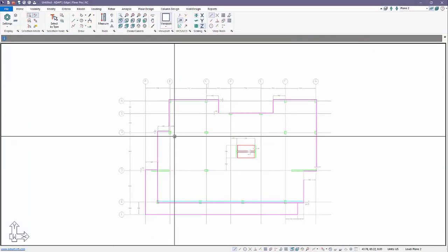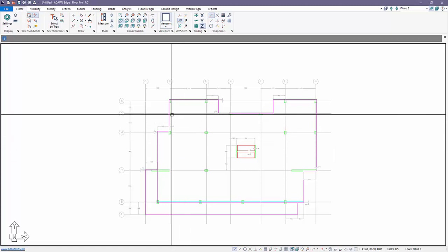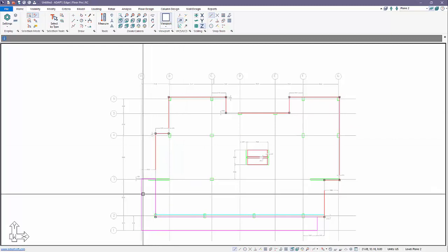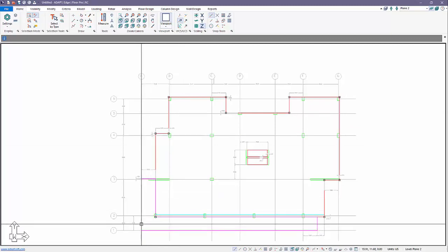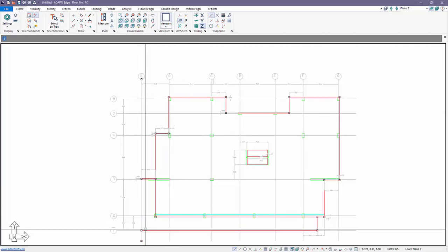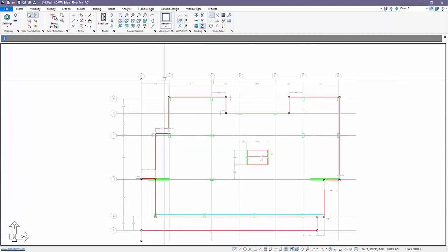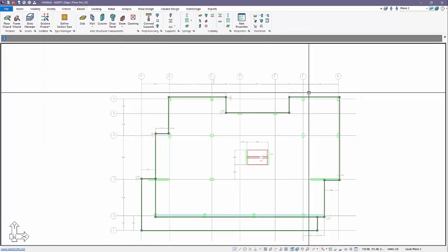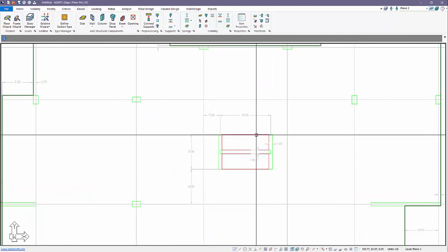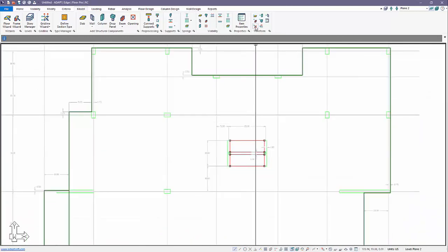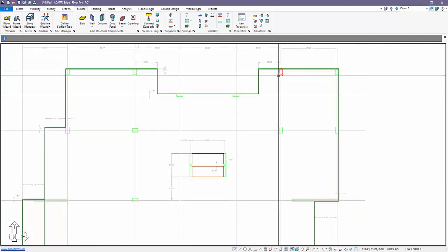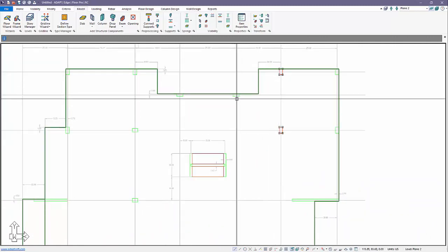The next thing we're going to do is we're going to transform components into polygons. So I'll select polygons. The slab, for example, is a polygon. This slab is also a polygon, so we'll select this slab and this slab. We have 2 slab regions. We're going to go over to Model. On the far right end, we have the Transform panel, and I'll transform these into slabs. I'll now transform openings in a similar manner. We'll use the openings option, and we'll just work through the model transforming these different components.